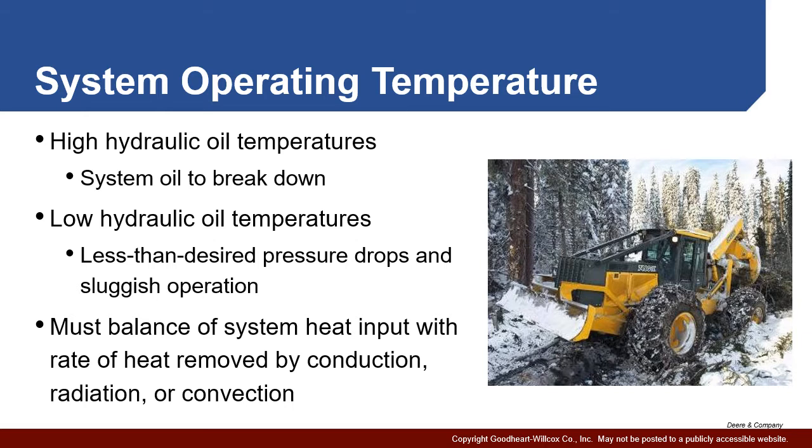Now, keep in mind, it's a balance because your system itself is generating heat, and your various components, particularly your reservoir, are conducting heat out of the system. The system also is radiating heat directly, and if there's any kind of air movement around, you might have convection. So you want to get it to that temperature, but then you want to keep it there by keeping heat generation and heat removed essentially equal, so there's no net change.